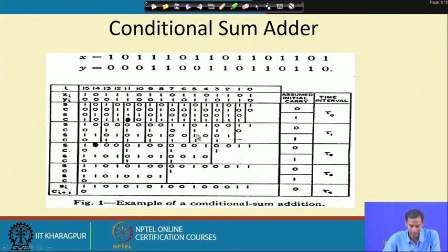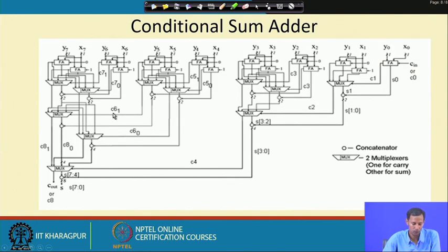Okay. So, now this again will affect what? This 1 and 1 will affect the 6 and 7 positions. So, again in this manner we have to find out, that means x6 and s7, sorry, s6 and y6, they will affect this y7 and x7. Then again from this multiplexer we will get a 2 bit group. A 2 bit group means one from this particular sum and one from the sum of this particular stage. Okay. Then again they will be selected based on the carry which is generated, that means if I take this as a group.